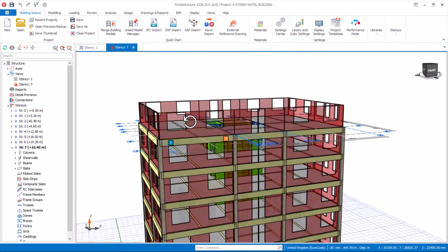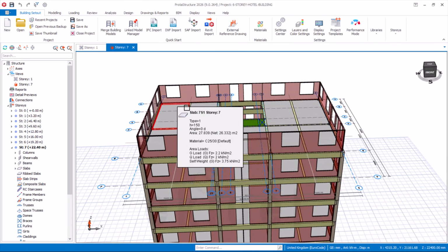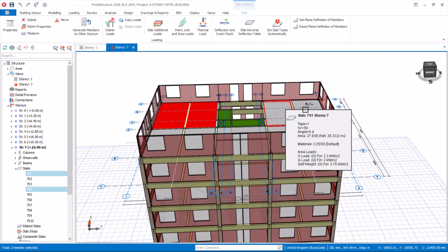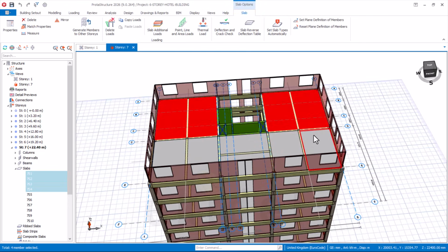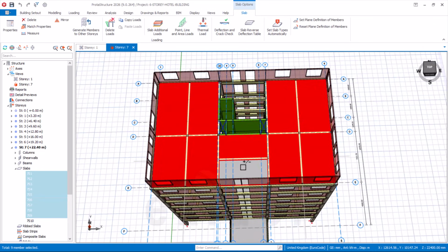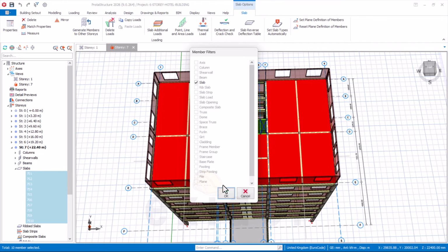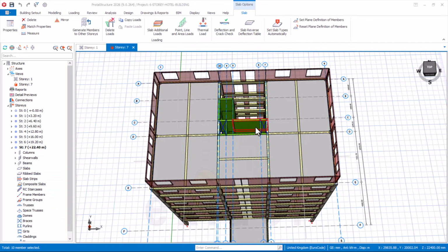So we are going to remove all the wall load here and the slab. So I'll click on this, hold my control key, and do a multi-select, else it will be hard. So I'll take time like this, and then select that. Then I click here and say delete. That is fine. And I'll say yes, delete all the slab.